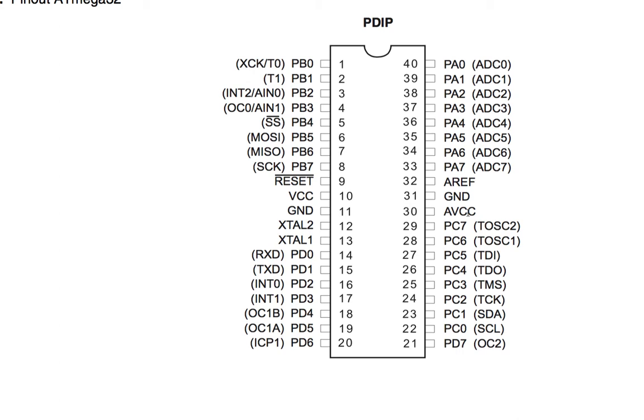Then the fourth thing that you're going to do is to select the input channel. You had set your input channel to be input, but which one exactly? Because there are 8 of them between 0 and 7. So how do you do that? You use the ADMUX, the multiplexing register, by using an ADMUX command in order for you to choose which one is going to be your usable channel in that particular program.